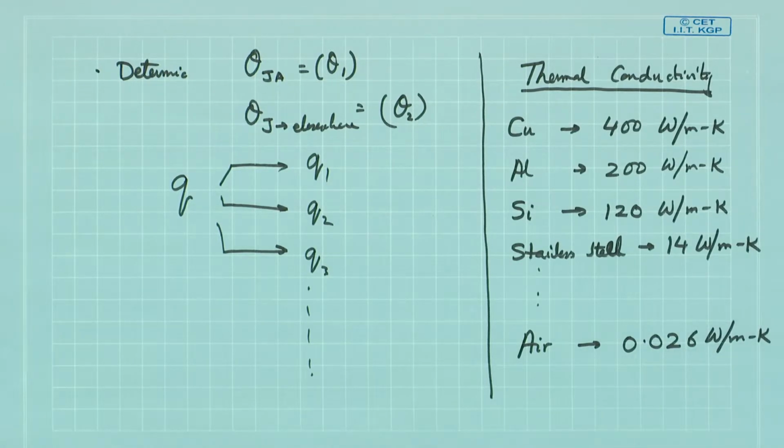It is not the window. How about ceramics? Ceramics will be single digit, like 3, 4, 5. And polymers, for example FR4, can be from 0.2 to 0.4. FR4 typically will be that. And when you have the wiring traces, then you have a KX, KY, KZ depending on direction. Is this with the glass in place, the number you gave for FR4? I think so, yeah.